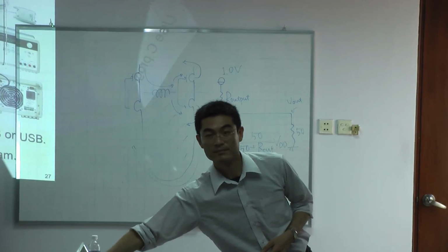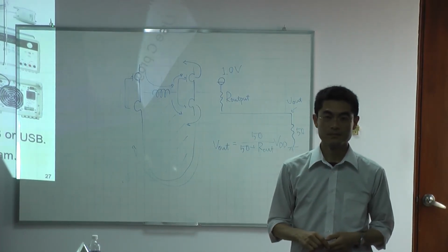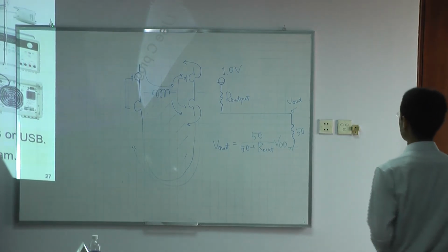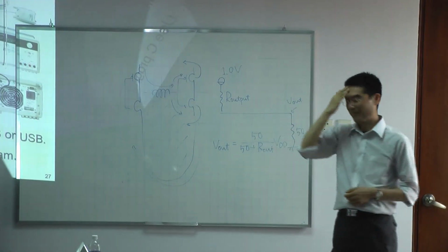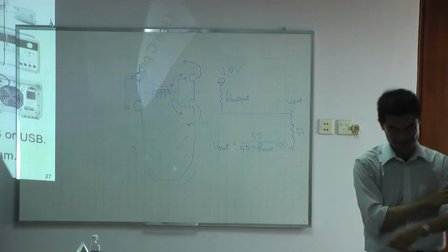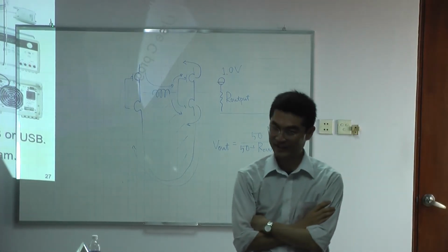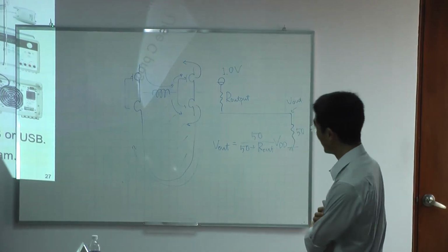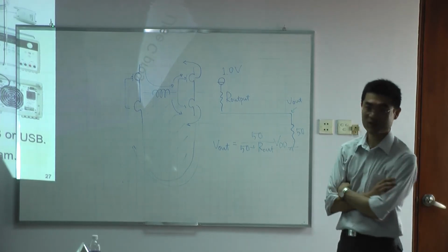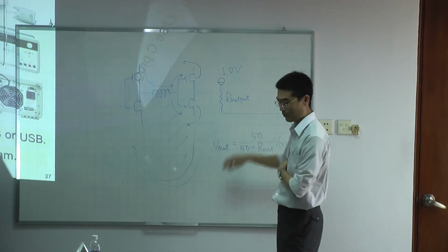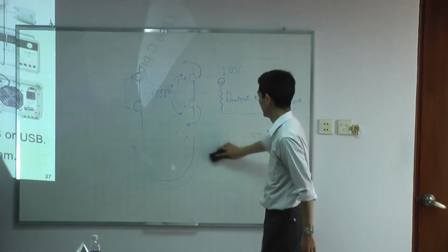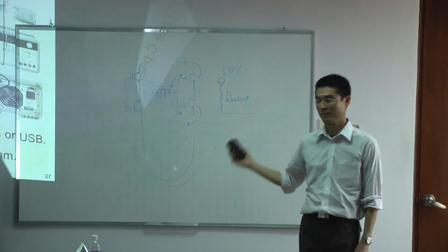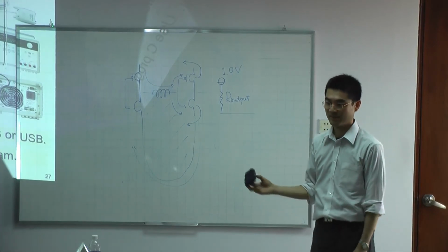Is there any other question? I get that the question is about the output impedance. Impedance means a complex value, so it means determining the phase too. I have to measure that, and if you really want to measure the output impedance, you output here, make this on, and measure using spectrum or network analysis. I haven't done that, but we can do it.